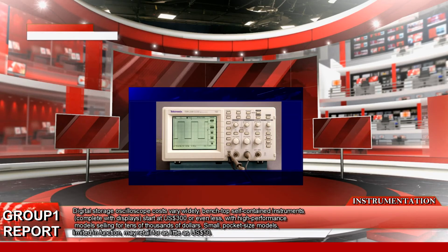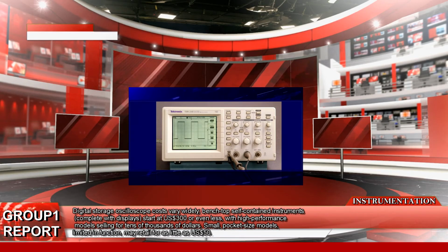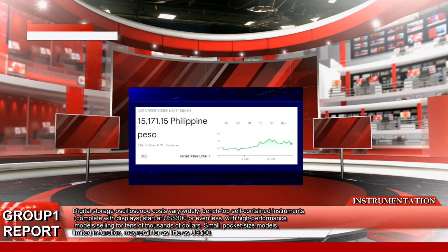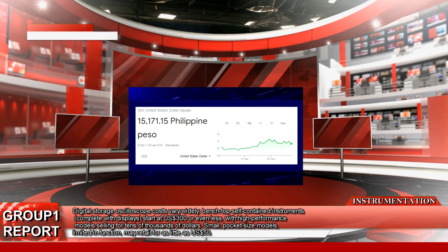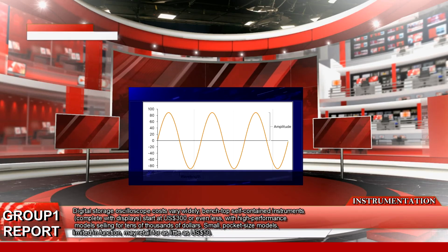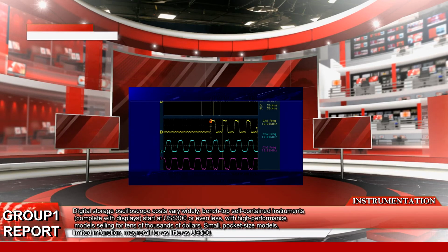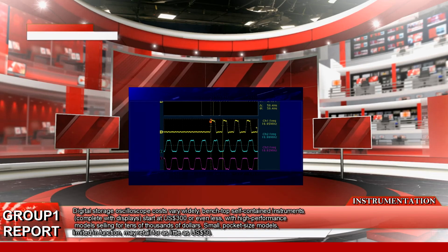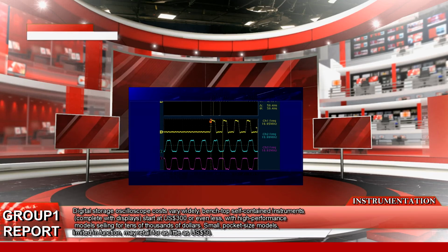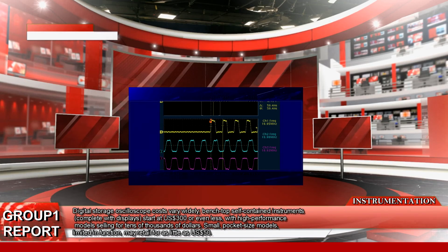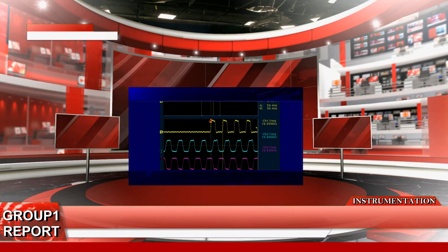Digital storage oscilloscope costs vary widely. Benchtop self-contained instruments complete with display start at $300. A digital oscilloscope usually analyzes waveforms and provides numerical values as well as visual displays. These values typically include maxima and minima, root mean square, and frequencies. They may be used to capture transient signals when operated in a single sweep mode without the brightness and writing speed limitations of an analog storage oscilloscope.